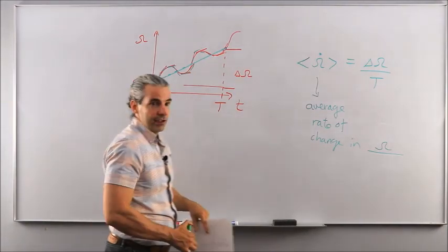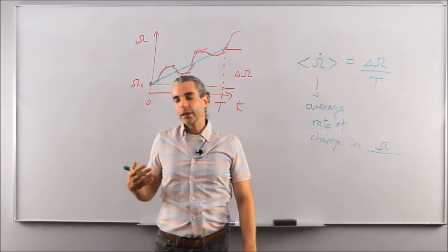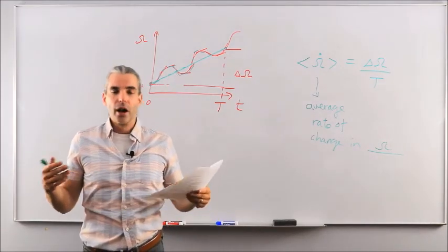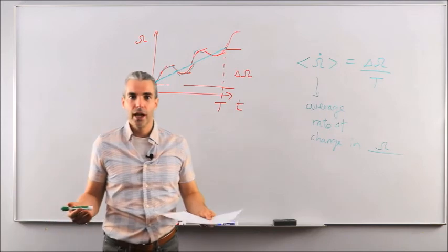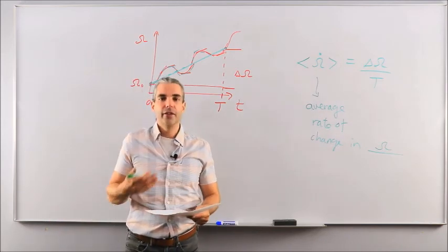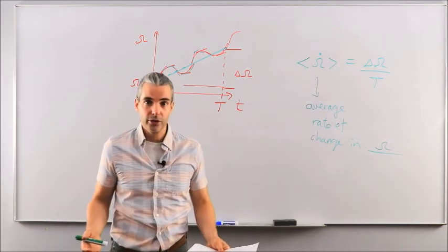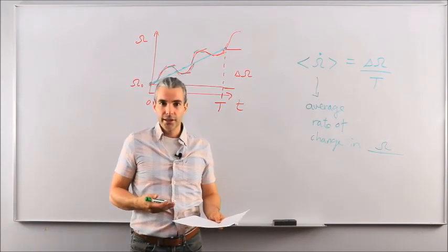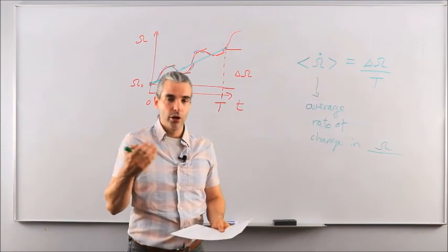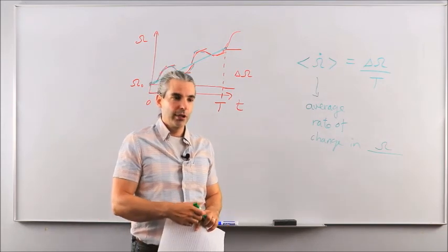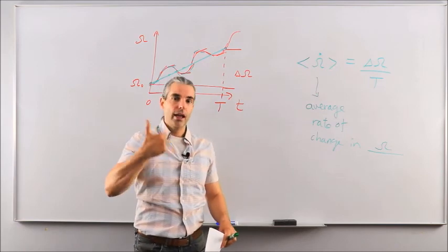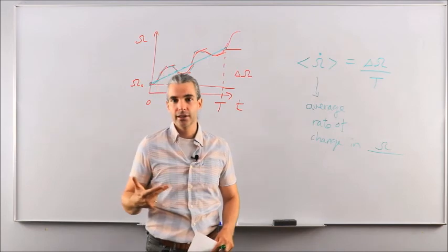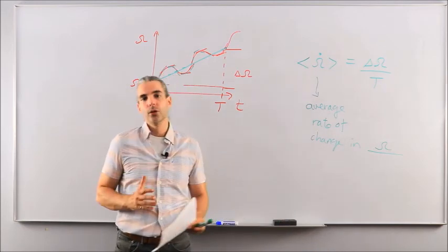So that concludes this introduction to orbital perturbations in terms of deriving the fundamental tool that we have at our disposal to analyze the effects of any kind of perturbations, right? All we need to do to use the tool, which is the GVEs, is to figure out the modeling of the perturbations such that we can extract F_r, F_theta, and F_z, so the x, y, z components of the net perturbing acceleration as seen in the orbital reference frame.